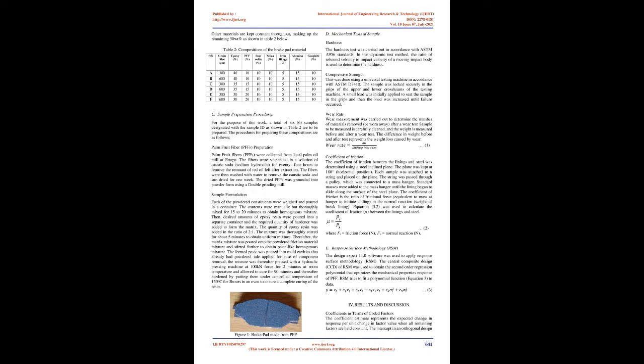Worked on the development of fly ash-based automotive brake linings. They developed friction composite using fly ash obtained from a specific power plant in Illinois. Additives such as phenolic resin, aramid pulp, glass fiber, potassium titanate, graphite, aluminum fiber and copper powder were used in the composite development phase in addition to fly ash.